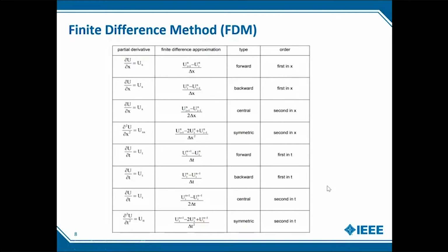And if you discretize at a very small time step and a very small spatial step, you'll have a much more accurate solution. So always remember, if you have a choice to use either forward or backward, always go for backward. Coming next is central, which is rarely used. Even the double derivative in time is rarely used. It's the backward. Most of the numerical schemes that you see use either first order backward or second order backward.